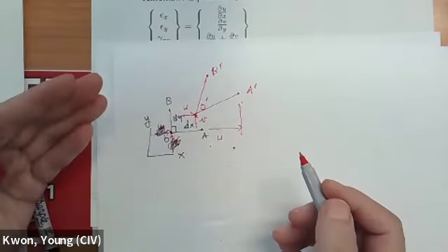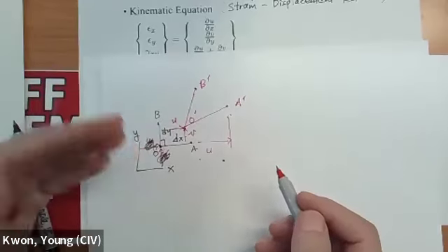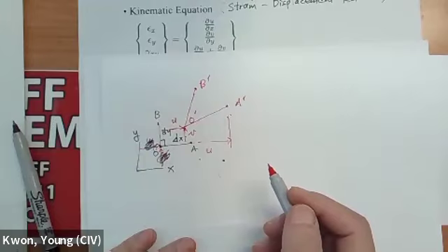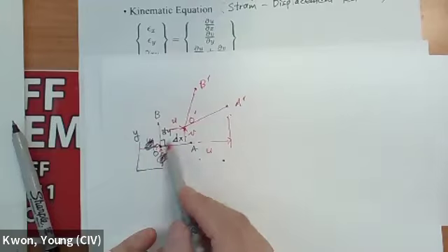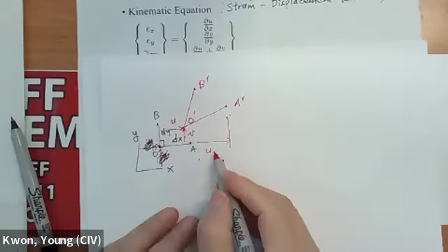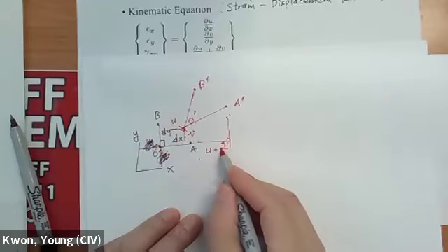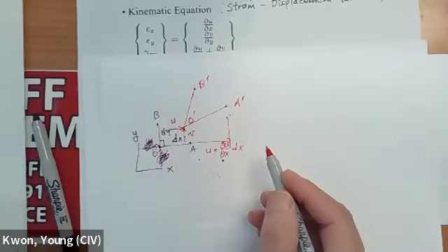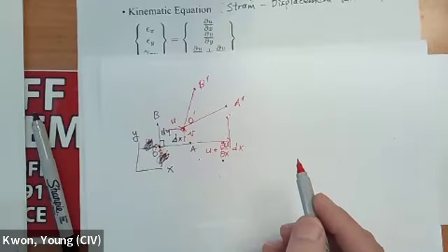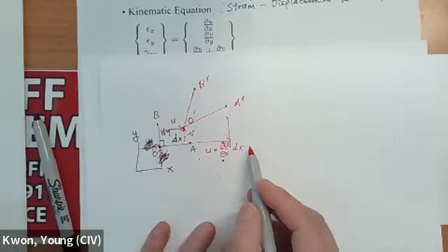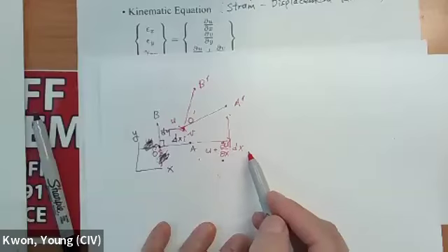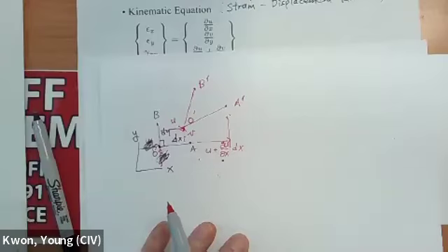Again, same concept we applied for the equation of equilibrium, using Taylor series expansion. So if the change at this point is u, then the change here is u plus partial du dx times dx. Make sense? And of course, you can add higher-order terms, but again, dx is so small that you can ignore those components too.